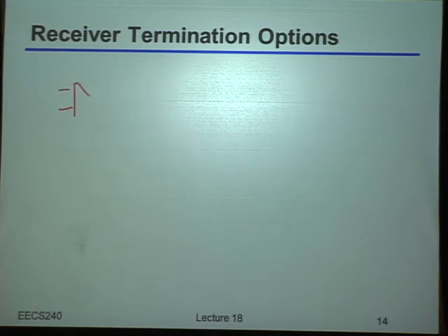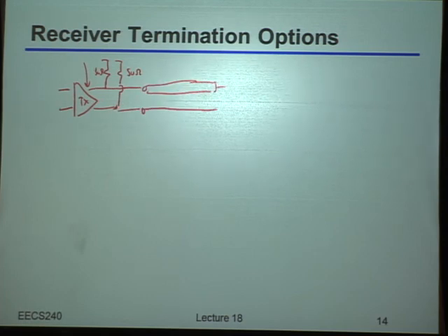Okay, so let's say we build our transmitter exactly the way I mentioned a second ago. Just inside of this box is that differential pair I had drawn. And so we have those two pull-up 50 ohm resistors, both tied to VDD. Then we feed those into the differential transmission line.